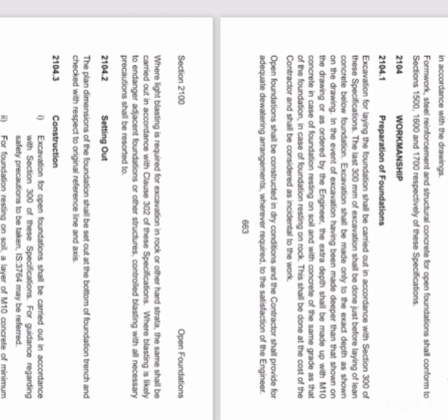2104 Workmanship. Preparation of foundations. Excavation for laying the foundation shall be carried out in accordance with section 300 of the specification. The last 300 mm of excavation shall be done just before laying of lean concrete before foundation. Excavation shall be made only to the exact depth as shown on the drawing.